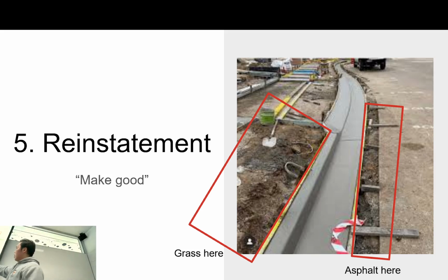So what you will need to do is, you'll need to take your road base and fill it up all the way to the top almost. Leave about 5 centimeters, and you need to pour asphalt, right? So you need to redo the road along there, okay?